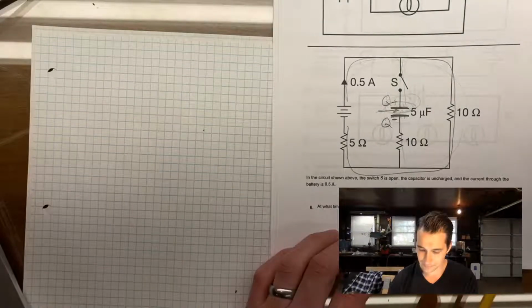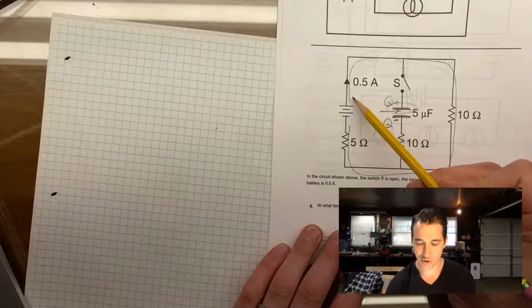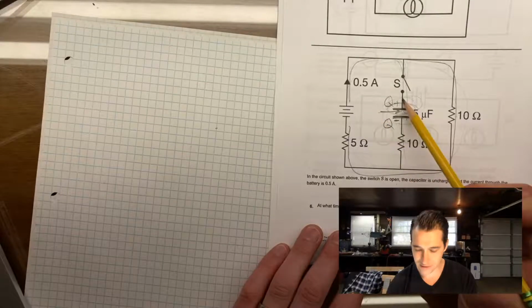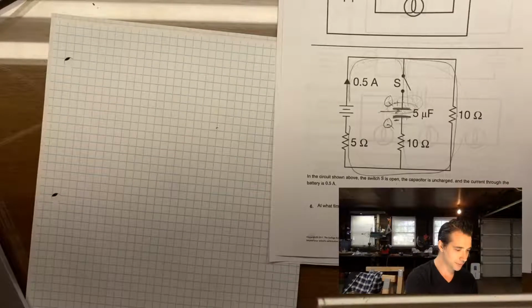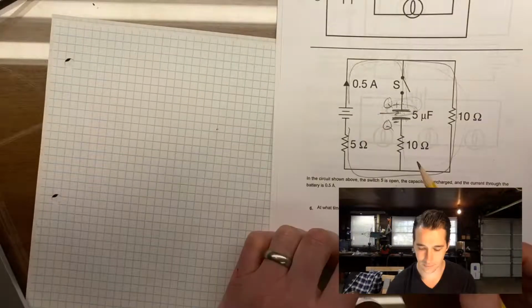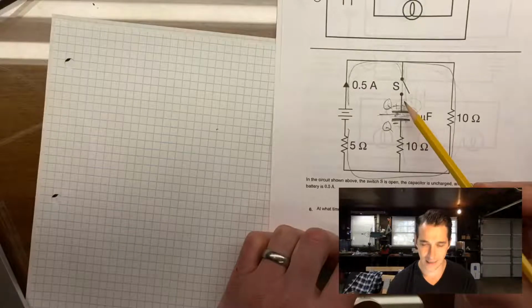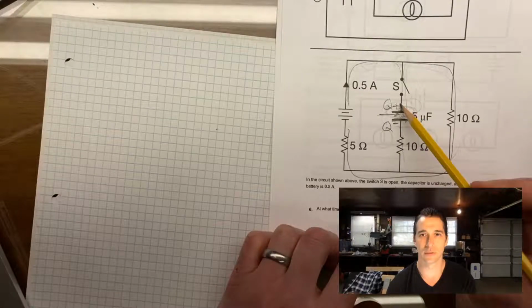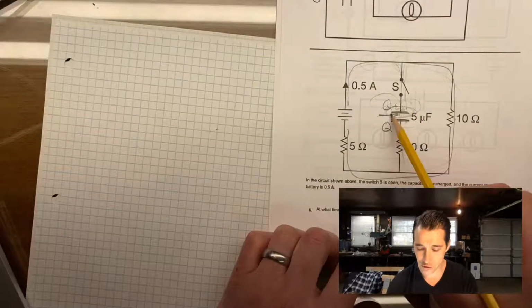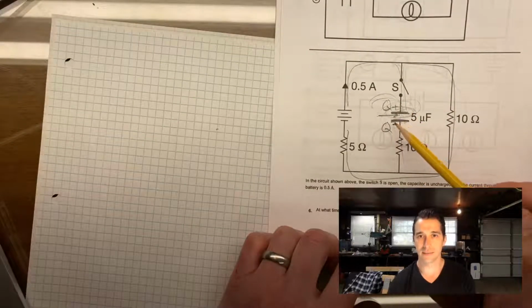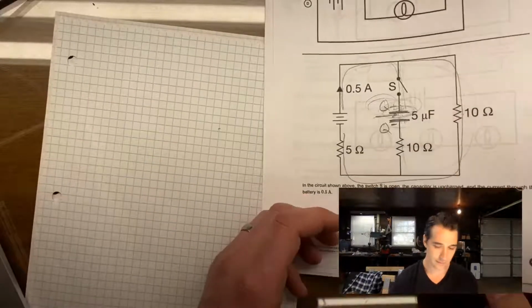Okay, that makes sense. So let's go back. It's uncharged. We close the switch. Now current will flow into this branch. Okay, so current flows in. Then what? Charges up. Once it's charged a little bit, less current will flow into that branch. Charges more, less current, less current, less current, until it's fully charged, reaches Q. And then no more current. So, what are our choices?